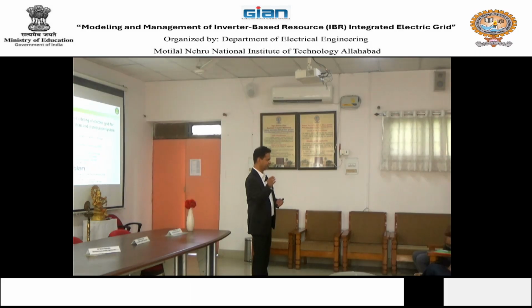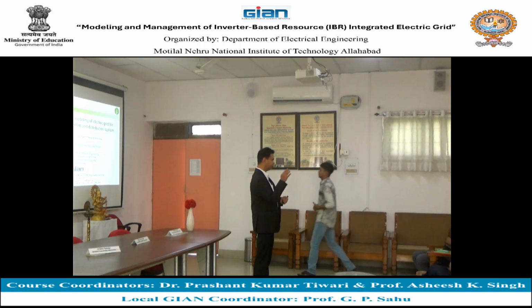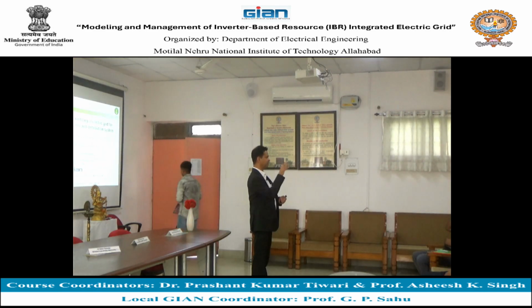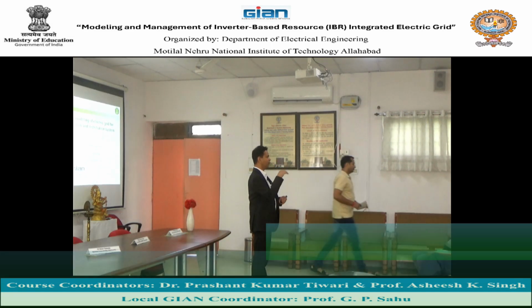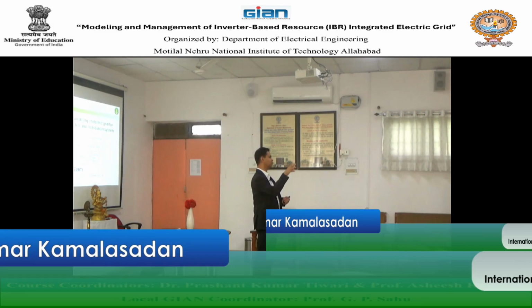Power flow is basically used to find out, if you are given a load on an electric grid, what would be the power transfer flowing through each line or each branch of the power network, how much will be the power at each point, power meaning active power mainly, also reactive power, and how much will be the voltage at each point.